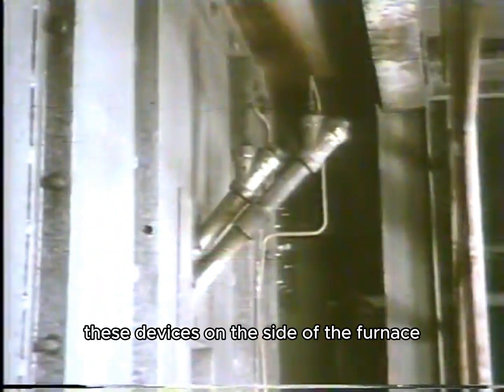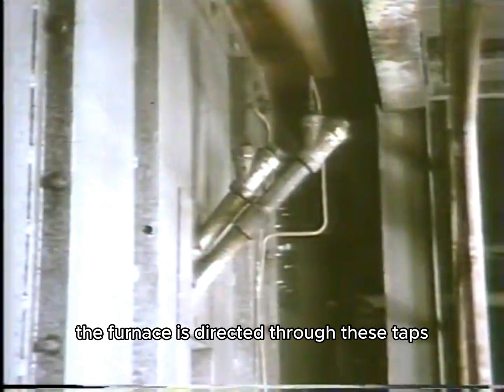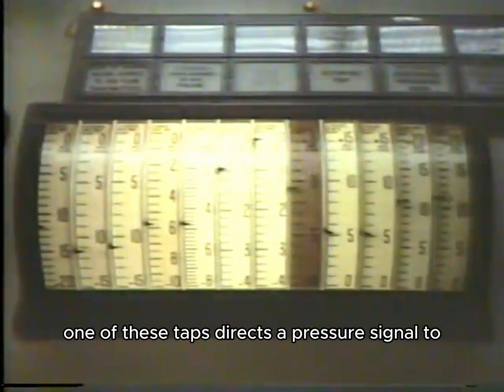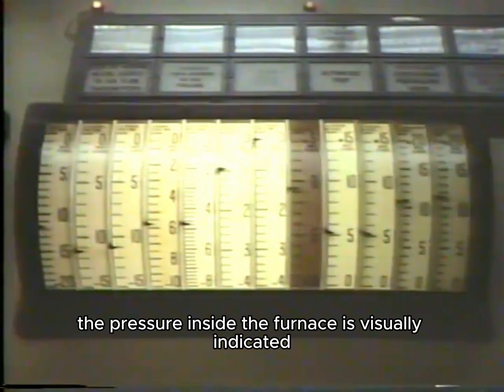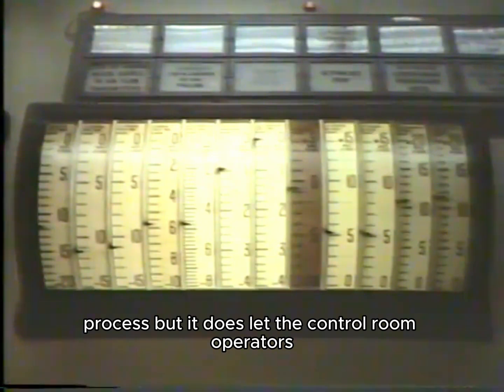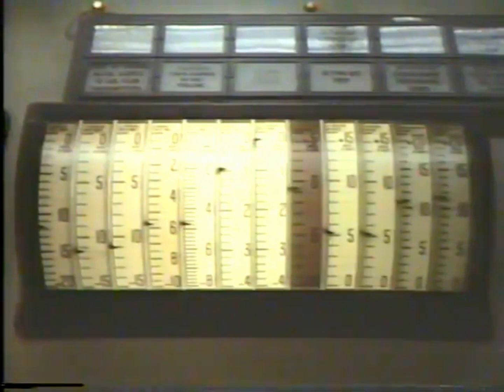These devices on the side of the furnace are pressure taps. Pressure inside the furnace is directed through these taps and the tubes to two locations. One of these taps directs a pressure signal to the control room, where the value of the pressure inside the furnace is visually indicated. This signal has no effect on the control of this process, but it does let the control room operators know what the pressure is inside the furnace.